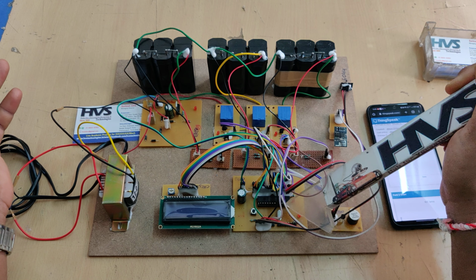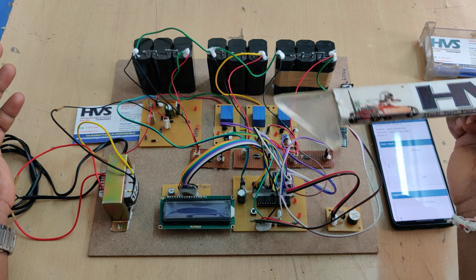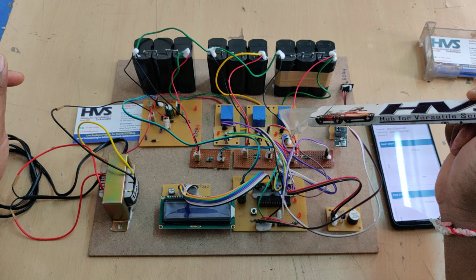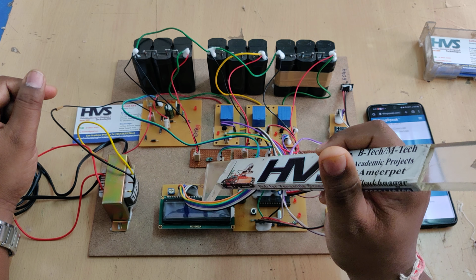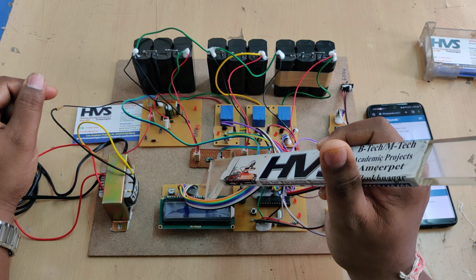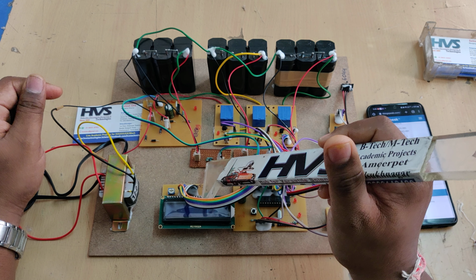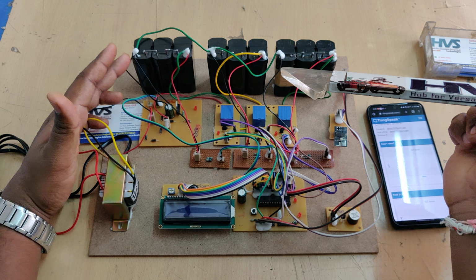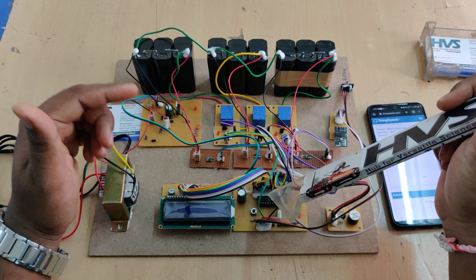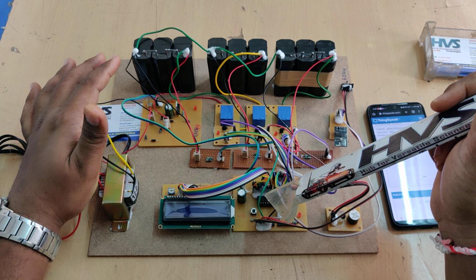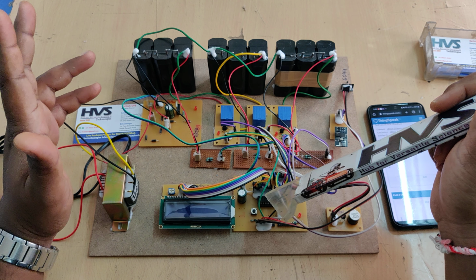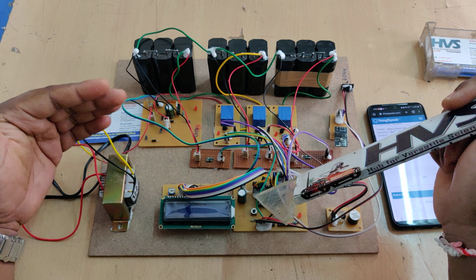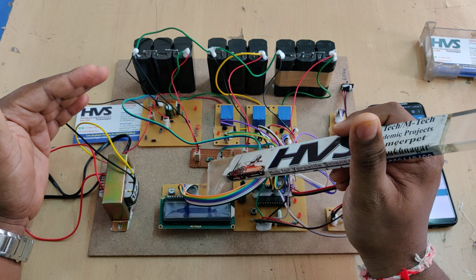Once we provide that to the microcontroller, it starts reading input from the sensors. The main sensors are first the voltage sensors, 3 voltage sensors for the 3 battery packs. Each voltage sensor consists of a 10:1 potential divider ratio, 10 kilo ohm and 1 kilo ohm. We are providing 12 volts DC to measure the voltage of the battery pack, but 12 volts is greater than 5 volts and the controller can measure up to a maximum of 5 volts. So to bring the 12 volts below 5 volts, we divide it with a 10:1 potential divider ratio.